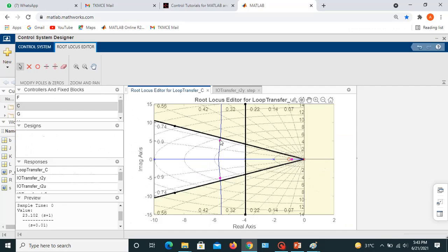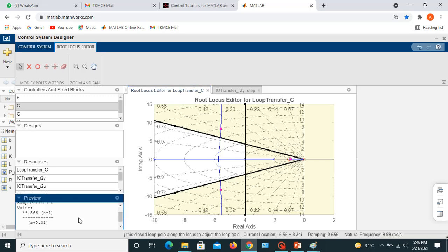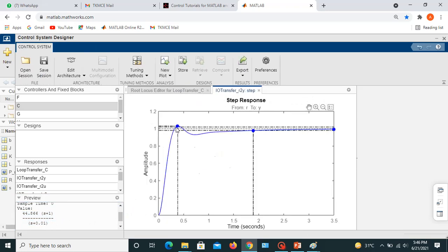As shown previously, we change the closed loop pole locations and check if the step response meets the requirements and then find the desired loop gain. Moving the closed loop pole out of the overshoot requirement line will increase the percentage overshoot, but here we are moving out of it by ensuring it is below 5% for the desired lag compensator. And finally, we can observe that the settling time is less than 2 seconds and the steady state error and the overshoot requirements are still met.